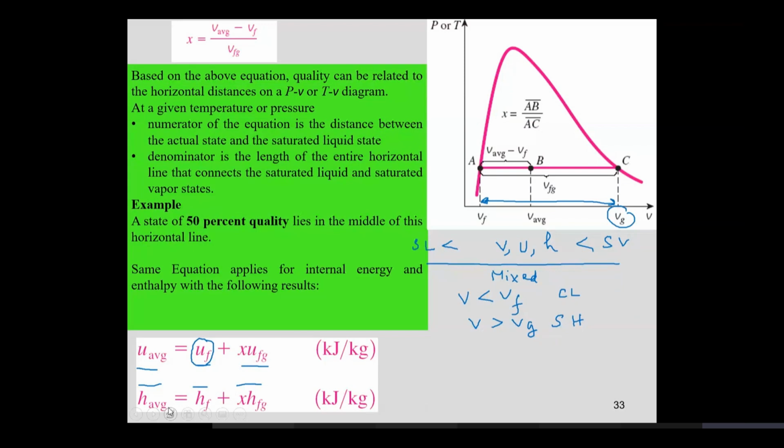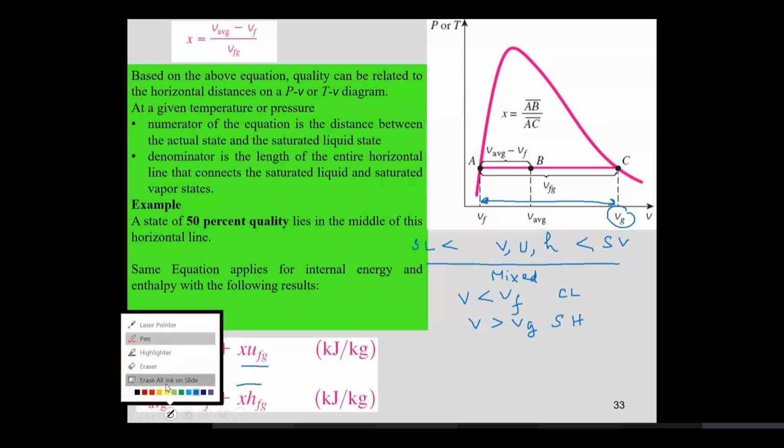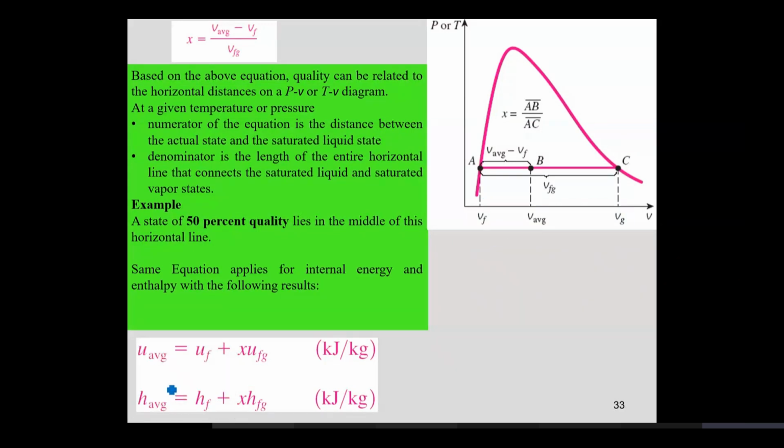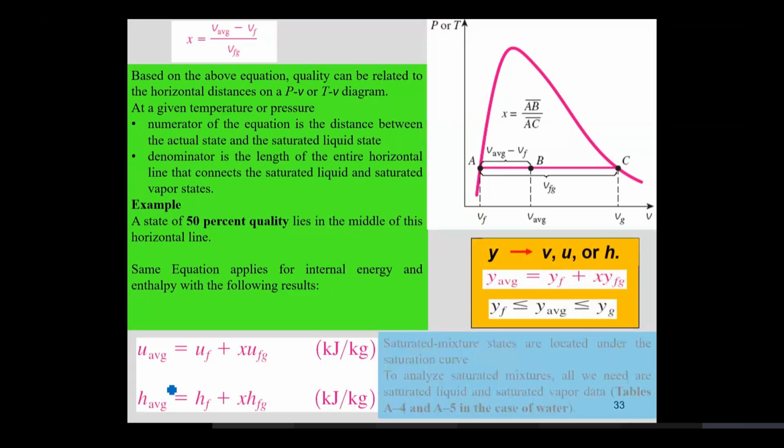All right, because you would have to identify which region you are in based on the values and the table. So you'll compare with the table and identify the regions yourself. You should have an understanding, based on the values, of whether you're lying in the saturated liquid-vapor mixture, compressed liquid, or superheated region. The same thing over here.